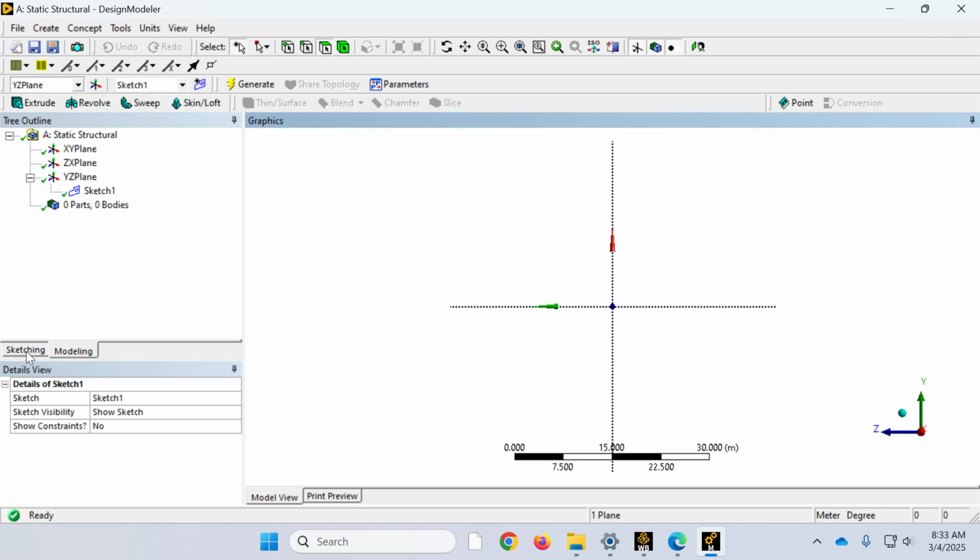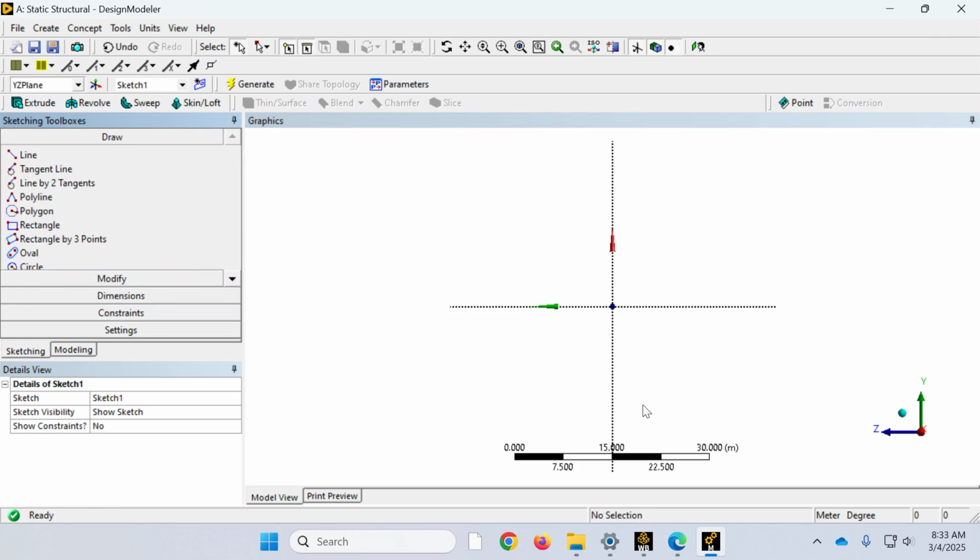And I'm going to toggle to sketching mode. I want to create a sketch that simply has a rectangle, right? Later on, we want to make sure we have edges on these faces where to apply the supports and apply the loads. Really there is more than one way of doing it. I can create these as four solids so I have these edges, or I can create one simple body, and then I'm going to show you that I'm going to be adding or splitting the surfaces to create the edge where I can apply my supports and loads. Either way is going to be fine.